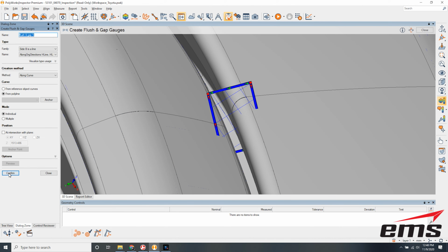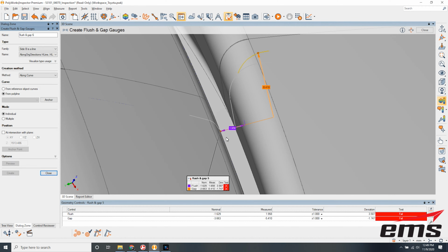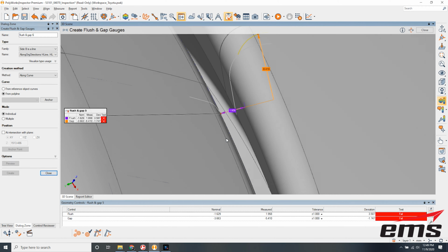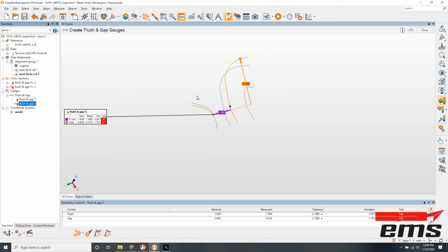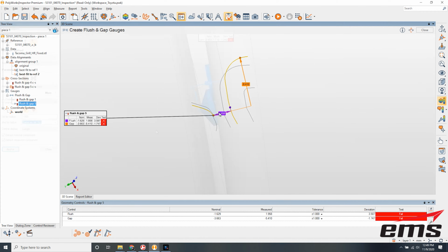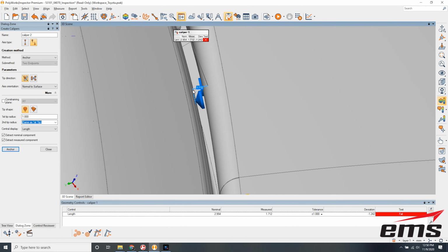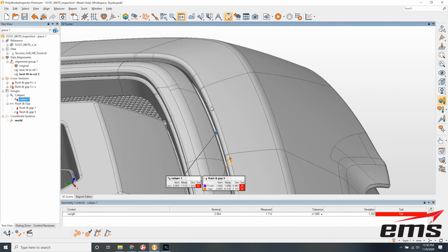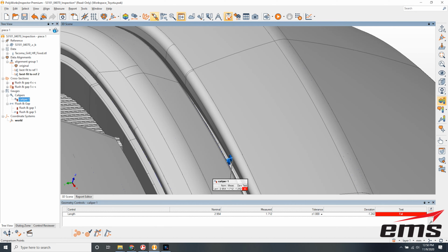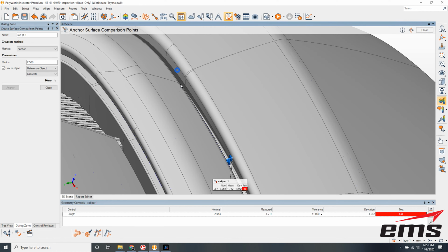To do these measurements, in this case we're going to use Polyworks inspection software, and we basically define the gap. We do some things to define the direction and location, and then we can go in and measure that gap distance anywhere along the part and pull out locations, or pull out that gap distance. So we can measure millions of data points all the way around this gap and put them in a report like you see here, and look at where there could be some issues. And again, we're doing this all virtually.